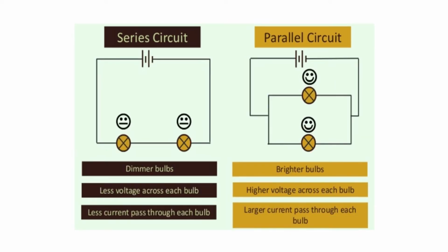Another reason why resistors are connected in parallel is that when it comes to the parallel circuit, the value of resistance is 1 over R, which is very, very small. So what happens is the current flow is going to be higher. In comparison with the series, the total resistance is quite large. Therefore, the current flow over here is going to be quite small.